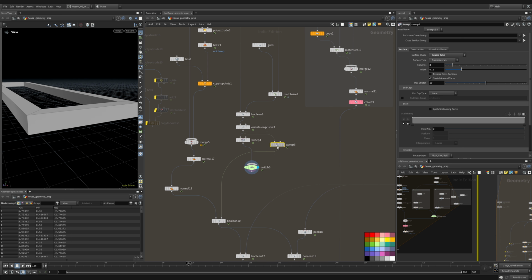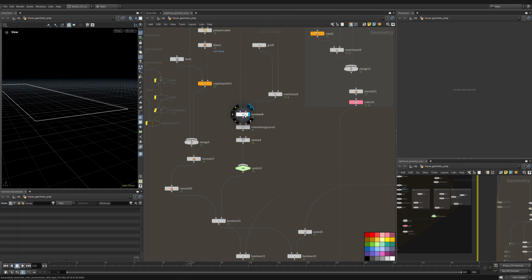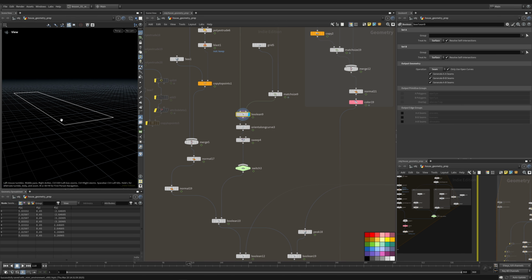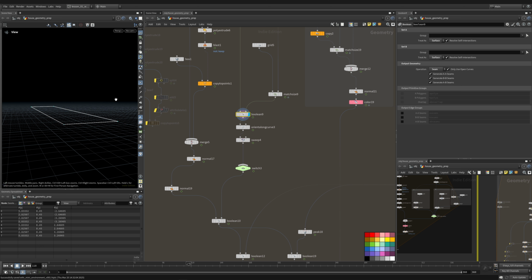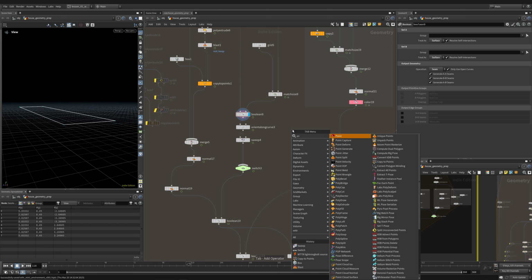Now if we wanted to do it a different way, what we could do, and I'll tell you actually before I do it, is I want to take this object, I'm going to duplicate these points downward, create a surface in between those points, and then I'm going to extrude that surface to be thick. So I'm going to do a poly extrude.